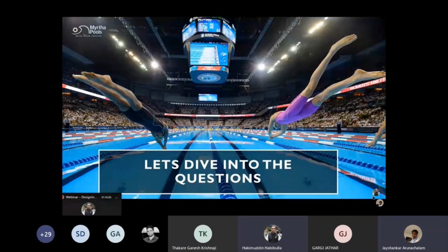But otherwise, yes, when we talk about diving in the swimming pool context, it's about jumping off a starting block. When you're jumping off a starting block, like I highlighted, 1.35 meters is the minimum FINA requirement, which is further defined as the depth required between 1 meter from the wall, where the starting blocks are, up to 6 meters from the wall. And these minimum standards are considered from a competent swimmer perspective. So that has to be kept in mind.